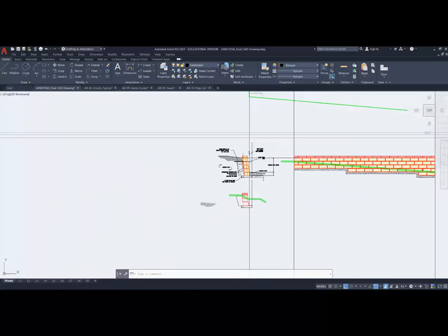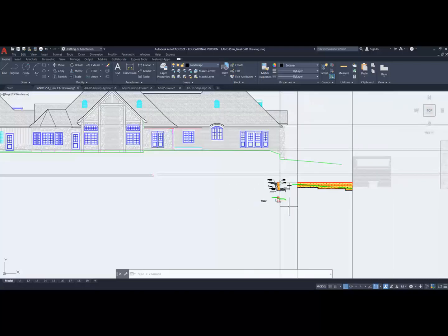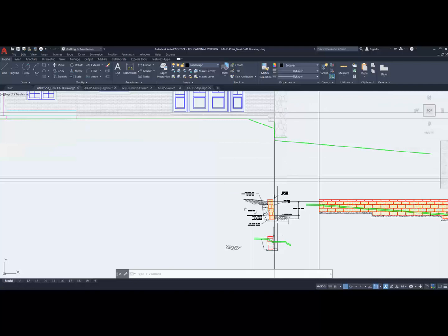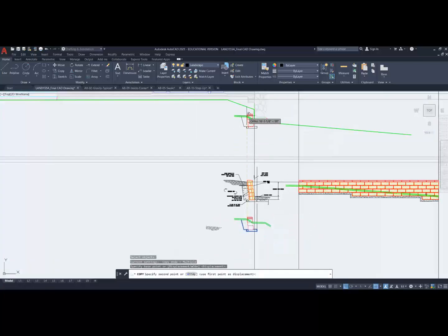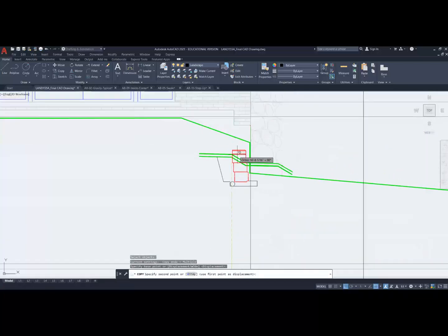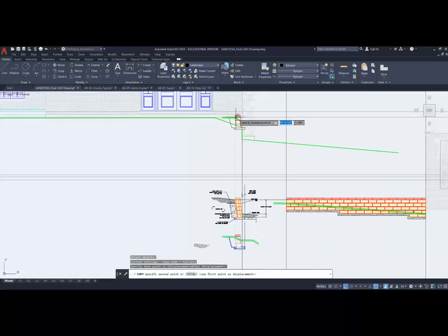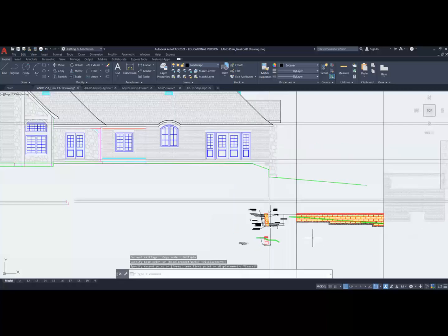And there's my end view, my sectional, and my elevational view along with the building face. And this is the view here that I can then copy onto the elevation. This is what it's actually going to look like when I bring this into the project. When I bring this into here, the top of that wall is going to stay continuous, and you can see then grade will adjust downwards along the length of the wall.